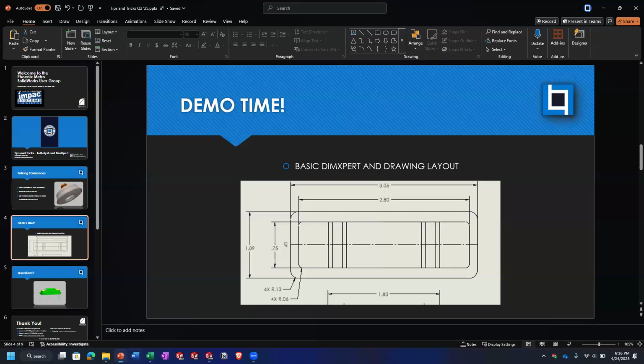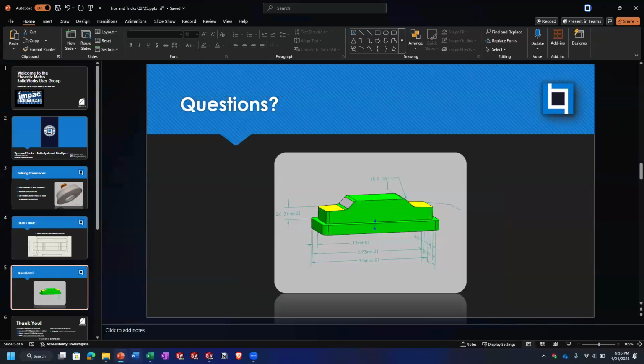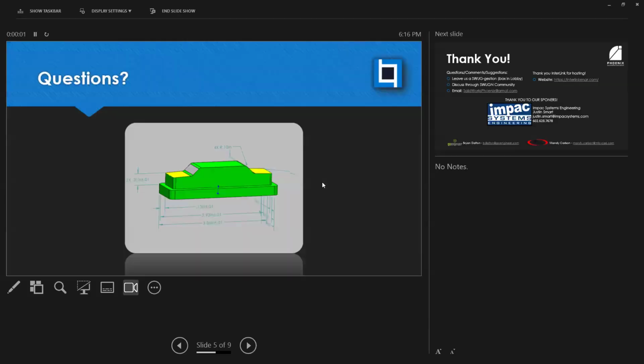My one thing is the parallel and the axis, right? Especially in a complicated assembly, it's very hard to see where the maximum influence is. There's orientation adjustments. He was using the root sum of squares, but there's an orientation tolerance as well, that will take into account parallels and then perpendicularities.